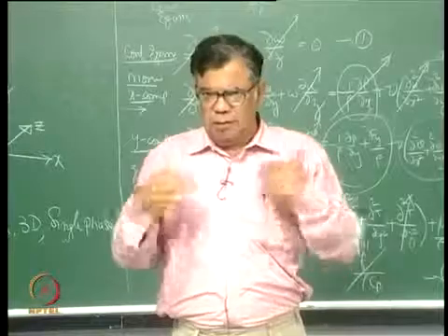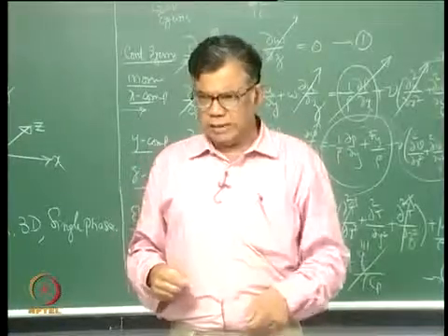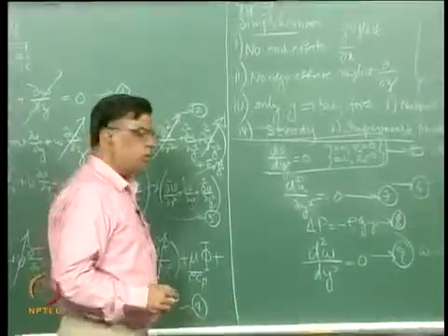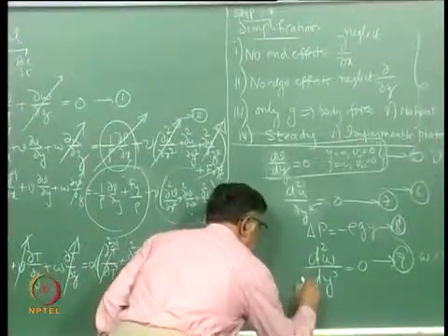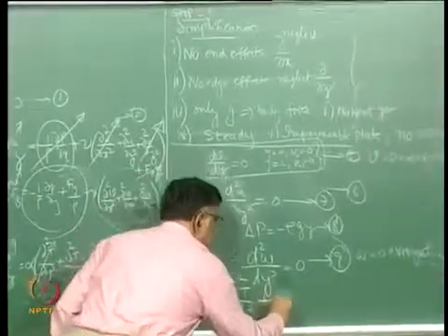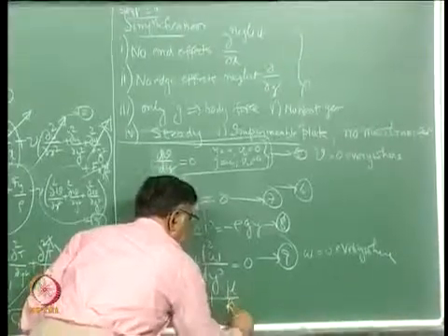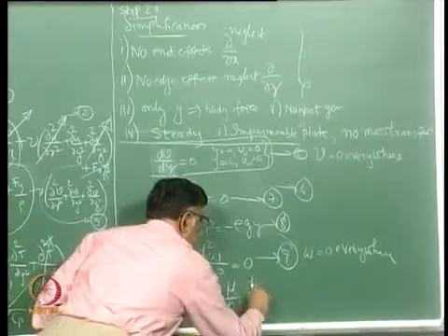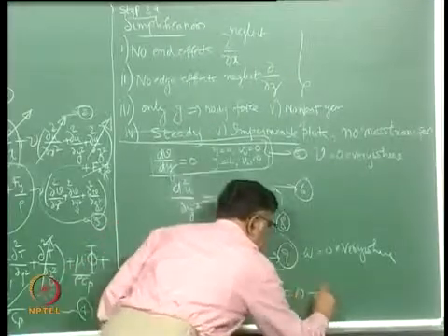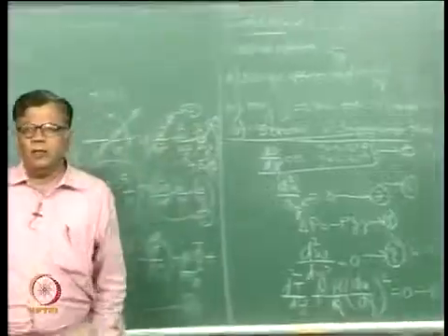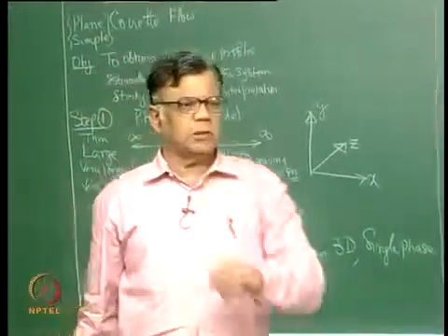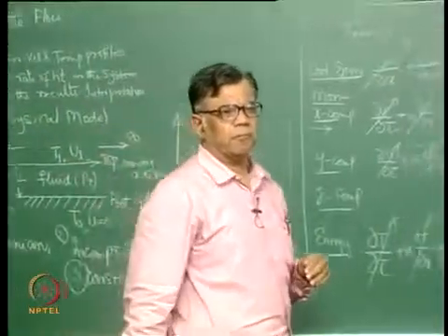Simply I will give that to you as a small exercise: do that and obtain the energy equation, all that you have written here, as simply d²T/dy² + (μ/k)(du/dy)². Where is this (du/dy)² coming from? From the viscous dissipation. Everything else cancels out there.